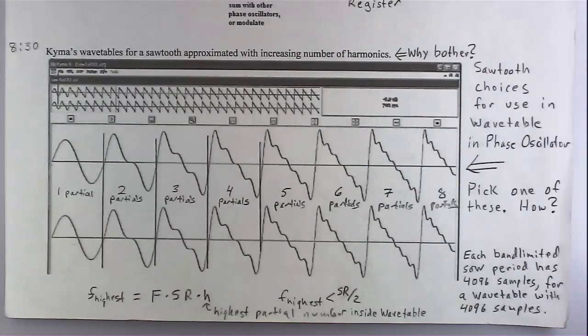And actually, you know this. Say you had a sine wave generator in the lab, and you sampled it. Well, every period of that sine wave, you hit different parts of the sine wave when you're sampling it. That's an exactly repeating sine wave, but when you're sampling it, you hit different parts each time through. Now, there's this weird corner case of my sample rate dividing exactly into the frequency of the sine wave.